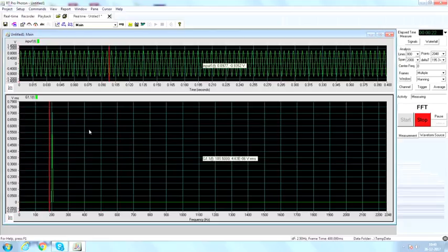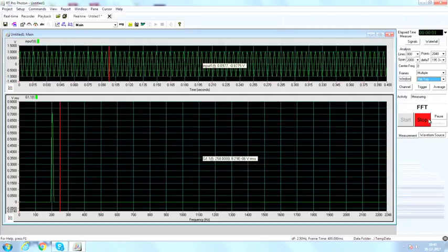So, if I come close to 200, see 200, 0.358, 202.5, I have got 0.707, and this is what I have demonstrated to you as the picket fence effect. Okay. I could have done the windowing. I have used a Hanning windowing function. I could use different types of windowing functions here. Okay. Maybe I will use flat top here. In this case, it may not show me much difference, but let me see.